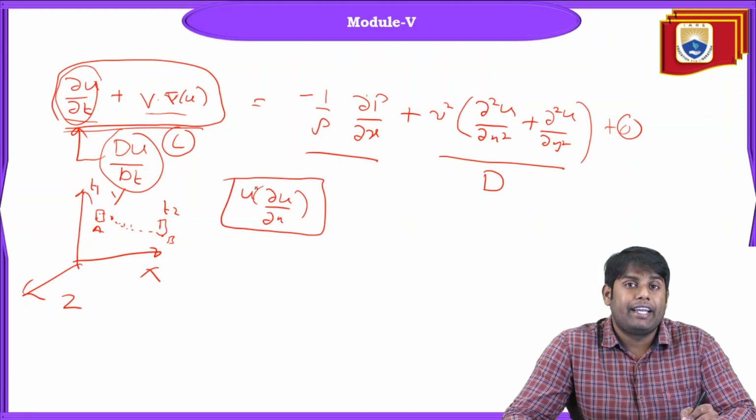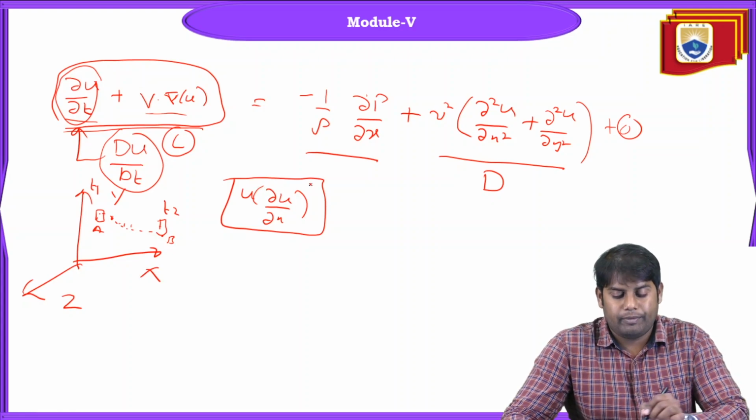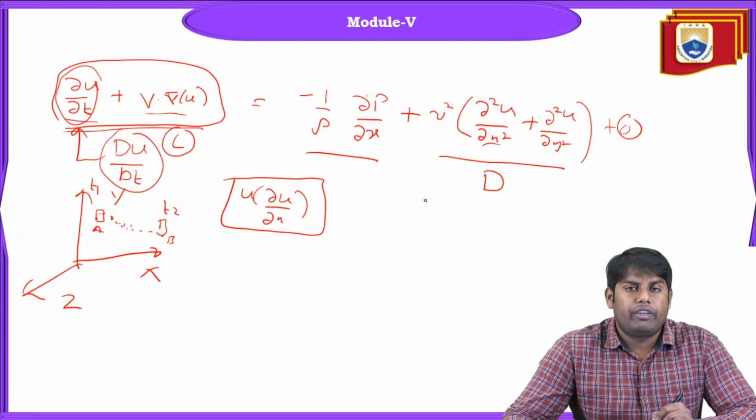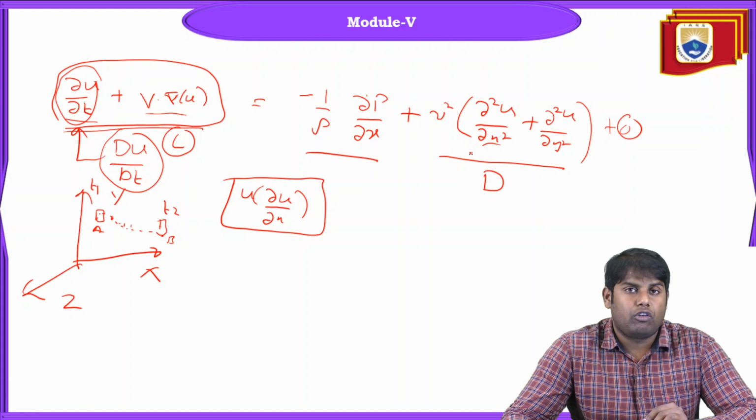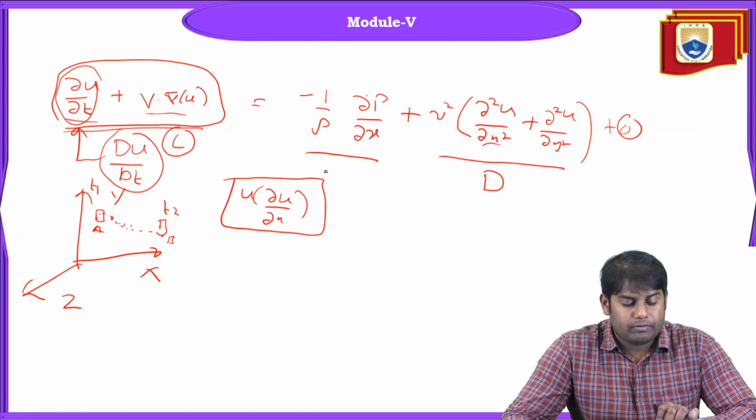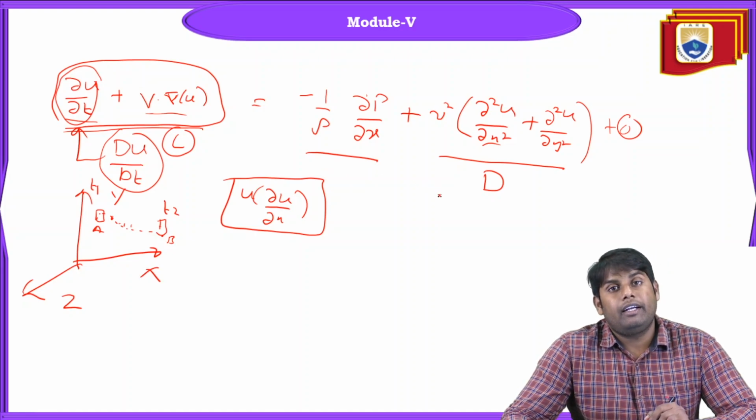So this is a non-linear entity. The non-linear entity is quite different from the second order term. When we see the finite difference formulation for ∂²u/∂x², we can directly write down the FDM method to discretize or make it in linear form, or in the finite volume method we can replace this. But for the non-linear term, we have to linearize them and then perform the discretization approach.